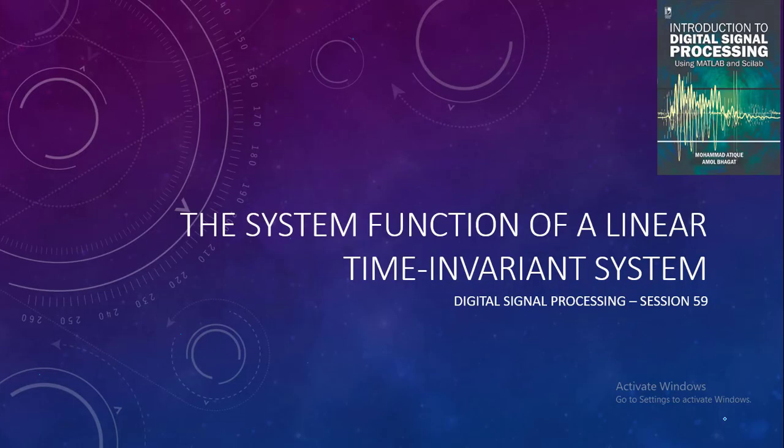In the previous session, we have seen pole location and time domain behavior for causal signals. Depending on the pole location, if it is inside the unit circle, we have classified it as a decaying signal. If the pole is on the unit circle, then it is a fixed signal, and if it is outside, then it is a growing signal.